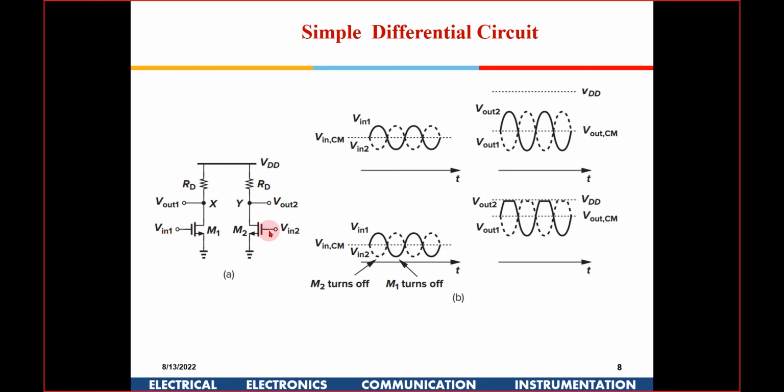I have Vin, two transistors. So this is Vin, which is given here, to this. So I have an RD coming in out here, and I have to give a 180 degree out of phase signal out here. So I get a V out here, the opposite signal out here. So if I take the difference between these two signals, this is one way of creating a simple differential circuit, okay.